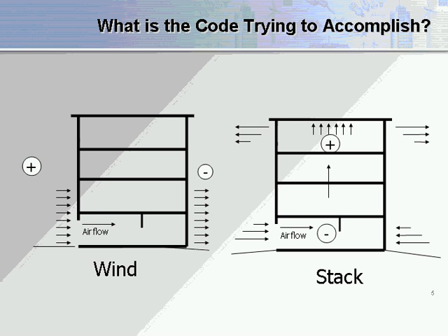So if we look at the left-hand, the wind section over here, we end up with infiltration from a wind load on a commercial building. Now, if this building is 4 stories and above, even in ASHRAE, this building would not be exempt. In the IECC, this building is not exempt. And you've got a wind load coming down through here into the opening into the building, and that creates quite a bit of infiltration.